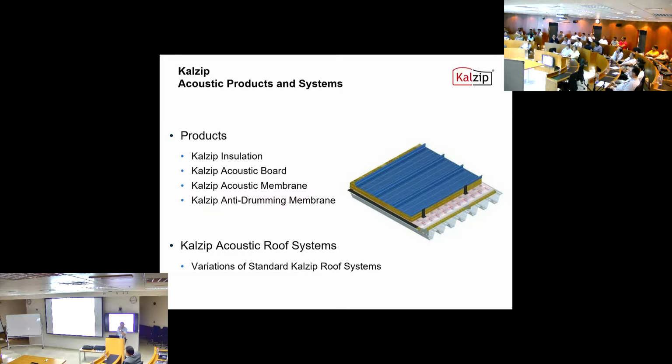Only for the liner, only for that system, the liner deck system. So we don't have to always use top hats. No. Structural deck system, we can fix the top hat, the clips directly to the crown of the deck. So we've got a lot of flexibility with what we can supply for various different solutions.